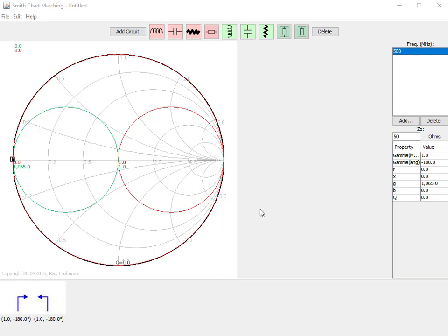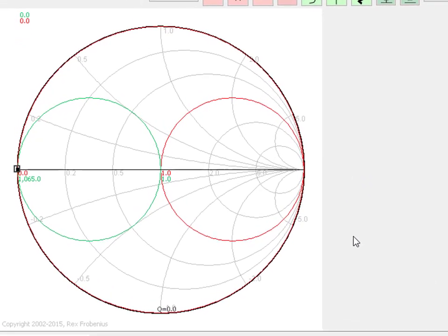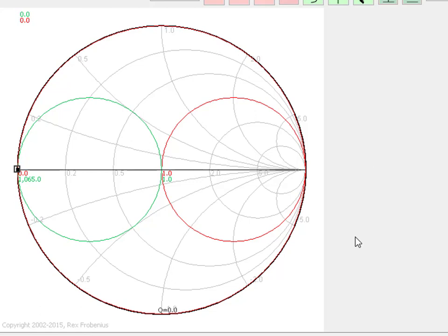When we look at the Smith chart, it's often difficult to remember which side is the short and which side is the open, particularly if you don't use the Smith chart all the time. But a trick that you can remember: the Smith chart is confusing because it's all these circles looped on top of each other, but at the center is this horizontal axis. And that axis represents all of the purely resistive terminations that you encounter. And just like a Cartesian system, it goes from 0 on the left to infinity on the right.